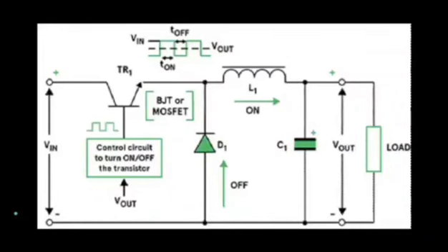Like other types of power supply, an SMPS power supply transfers power from a source, usually an AC outlet, to a DC device. What sets the SMPS apart is its ability to regulate the output voltage. It can increase or decrease the output voltage to maintain a constant output regardless of changes in load. This dual ability gives it an advantage over linear regulators, which can only regulate the output down. That is, they can only decrease the voltage and not increase it.